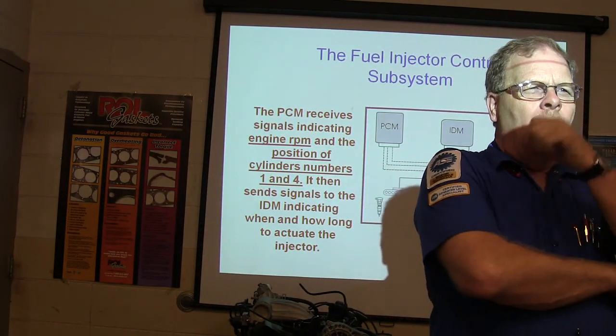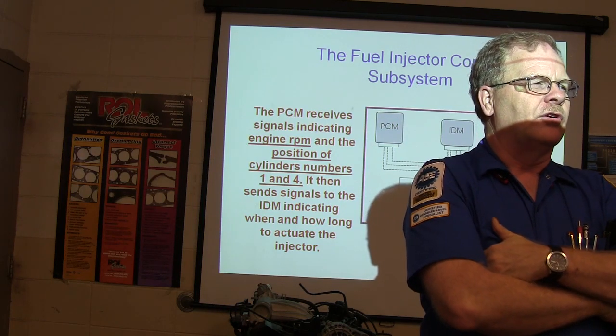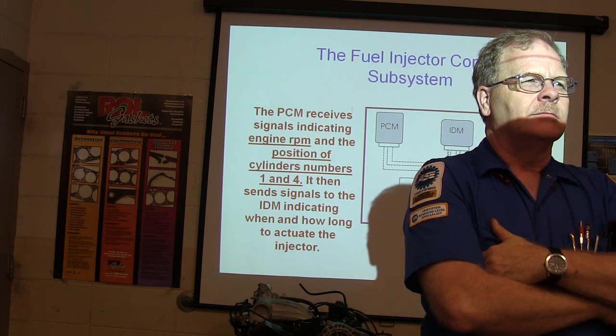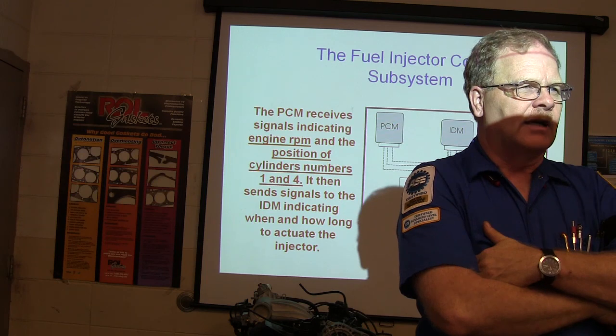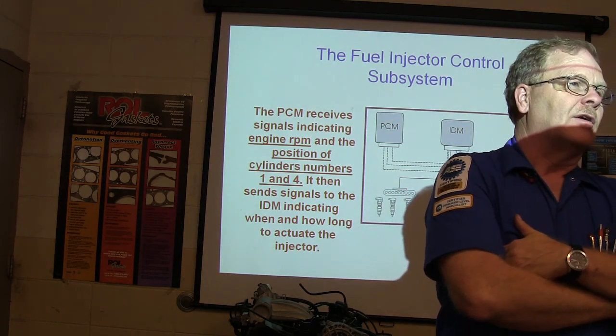Now, what is the firing order on an old 302? An old 302, you remember? Anybody know? You know you're supposed to have all those firing orders memorized, the ones I've always telling you all the time. 154266378. That's the firing order on one of those.